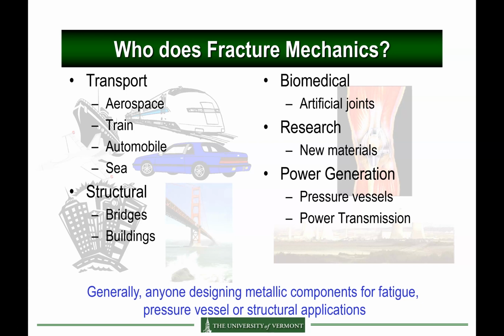And then in power generation, a very famous problem of fracture is in the installation of pipelines for transport of gas, of oil, where a machine during installation will create a defect in the pipe, and under pressure that defect will exceed the fracture toughness and cause the material to fail. In this case, the propagation of the crack is catastrophic, on the order of kilometers per second.